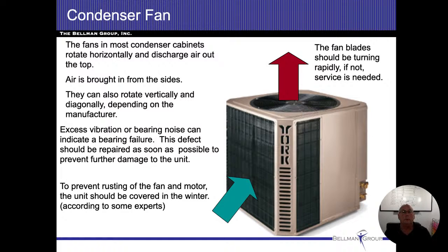They can also rotate vertically and diagonally depending on the manufacturer. That's true. You should hear a hum. You should hear a minimal vibration coming out of it, but it shouldn't be loud. It shouldn't be rattling. It shouldn't be shaking. Those are all things that could tell us that we got some bad bearings or something that's getting to the end of its lifespan.